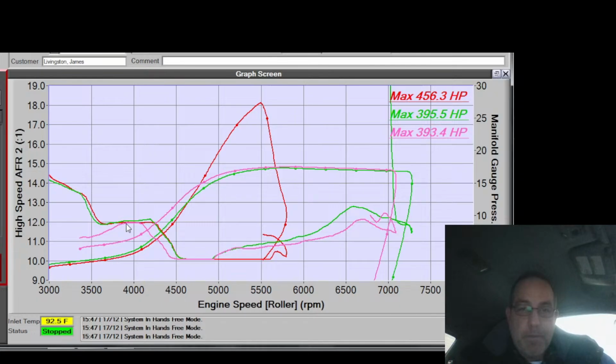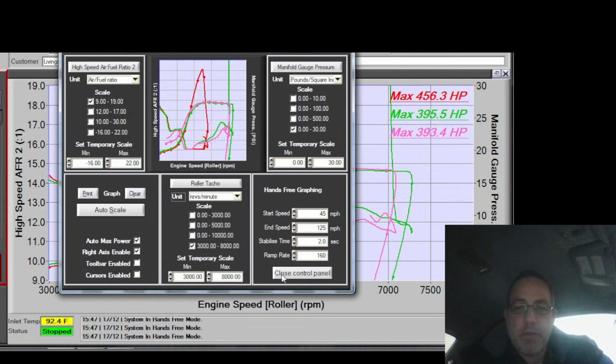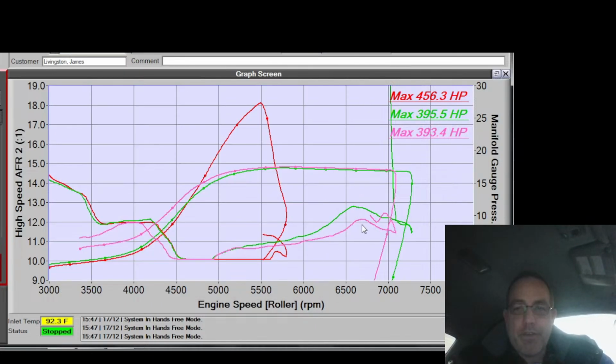It assures that it stays there, and then it pops to open loop and then goes too rich right here, which will impact the spool some up in this area as it gets too rich. So I can, and I will, lean it out here, which will aid the spool. I'll add some wastegate duty cycle. That will aid the spool. But overall, this still is not a comparison. I'm really surprised by this. Honestly, I'm really surprised by that. I added a lot of fuel, and it did not bring it down as far as I thought it would.